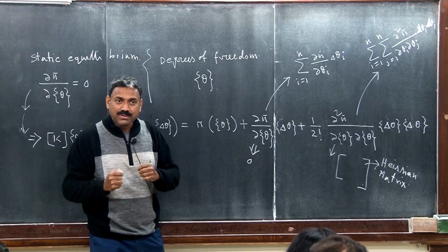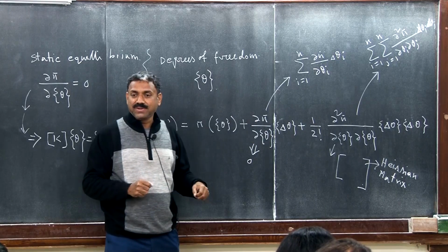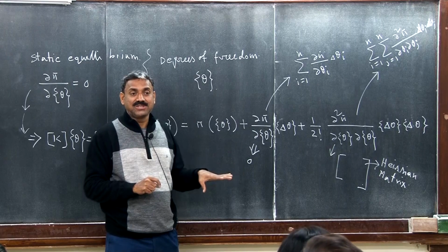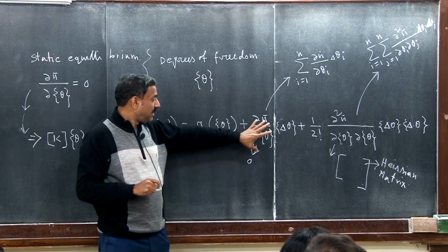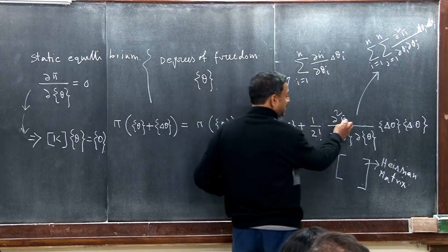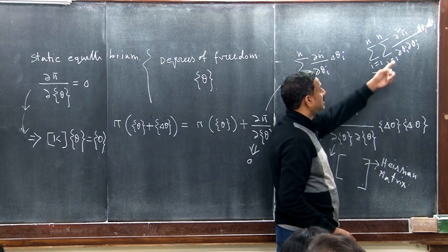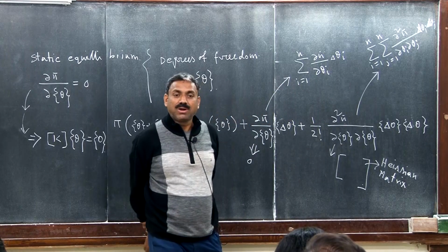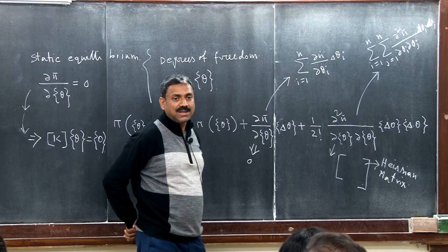So now, because of that perturbation, if the alternate configuration has higher strain energy, then the equilibrium that we are attaining will be stable. That means if this is greater than 0, because these are appearing in square, delta theta i, delta theta j, so basically this will always be positive. So this term needs to be positive.